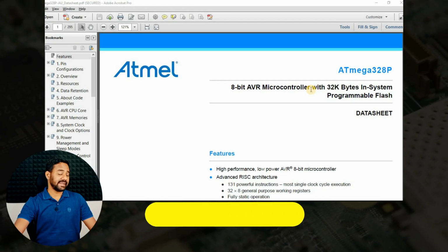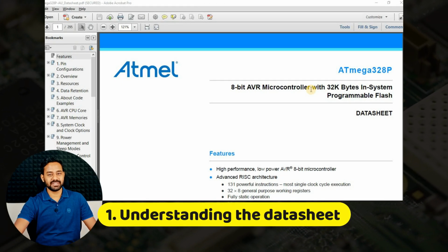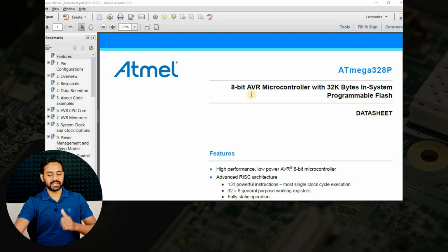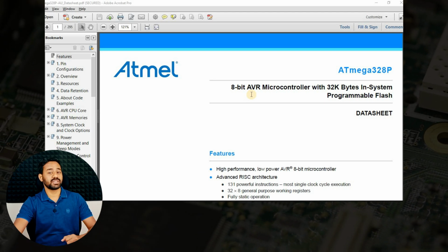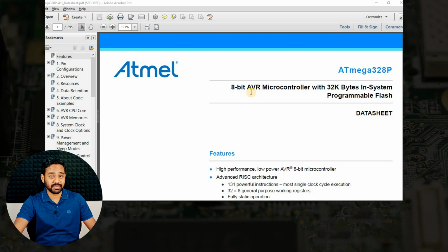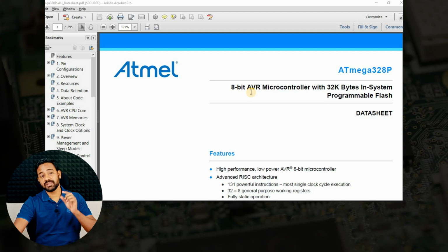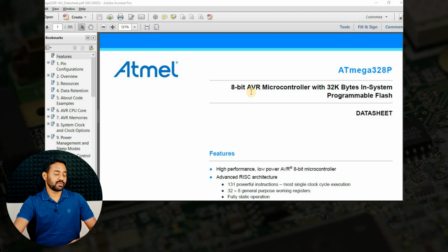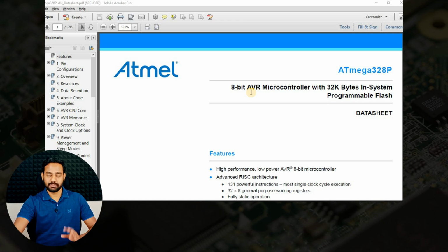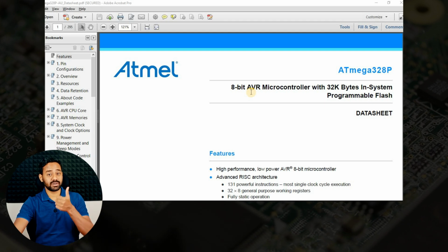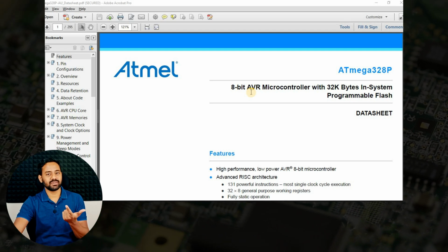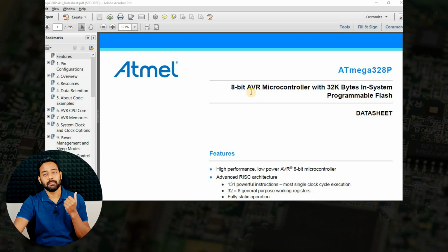Now we can see the datasheet of the Atmega328P-AU microcontroller. It is available in 2 different packages. One is a TQFP package, another one is a QFN package. This datasheet consists of all the details that a developer, a hardware design engineer, or maybe a firmware developer should need. Of course, reading this datasheet requires a lot of time to understand all the packages and details, but what we are focusing on now is the ordering information and the schematic symbol representation or pin diagram, and then we are going to focus on the mechanical detail.